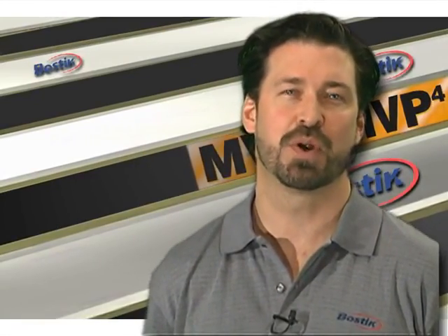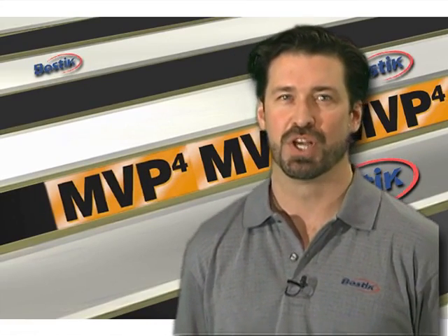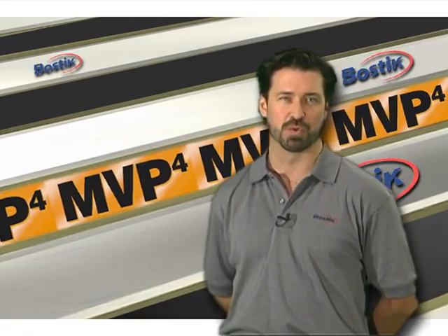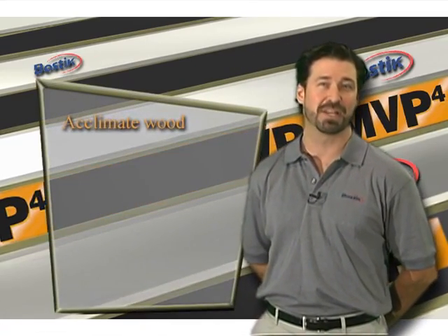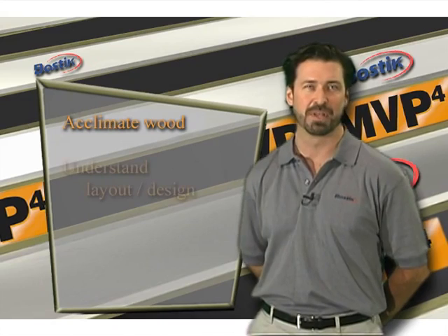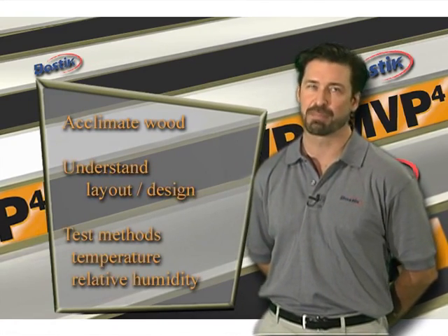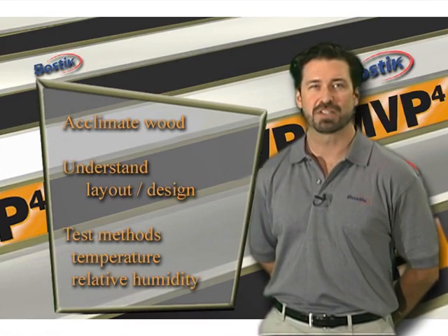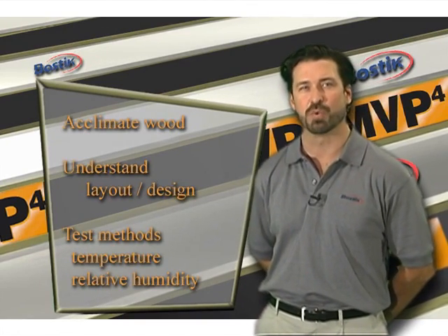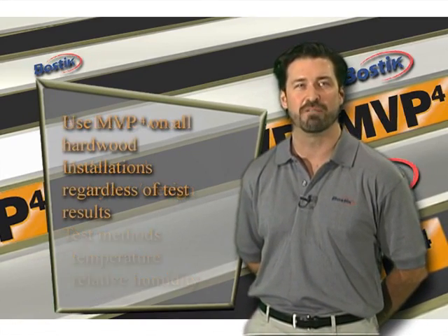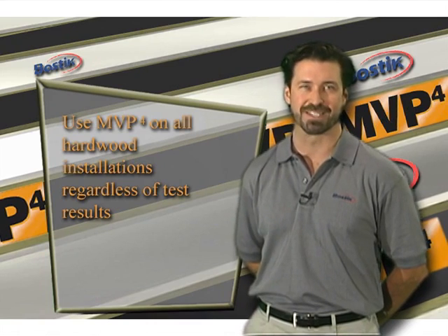To ensure the future success of your wood flooring installation, it's critical to conduct a thorough inspection of the job site. And prior to your installation, make sure you follow industry standards, as well as the wood flooring manufacturer's recommendations regarding acclimating the wood in the finished constructed building, understanding proper layout and design, and test methods, including temperature and relative humidity. Since a subfloor's moisture composition will fluctuate constantly throughout its life, it's best to be on the safe side and install MVP on all hardwood flooring installations.